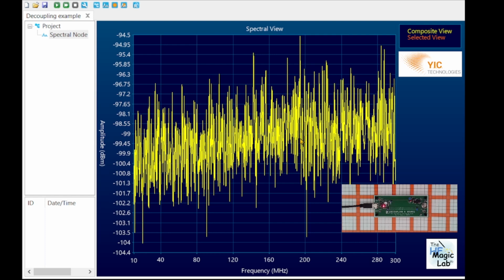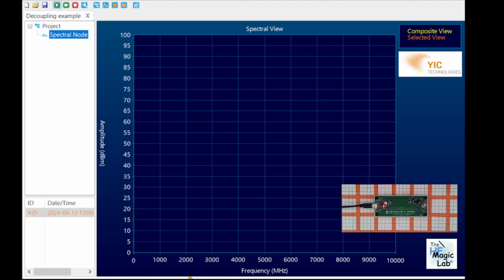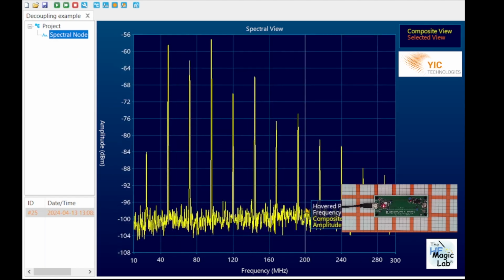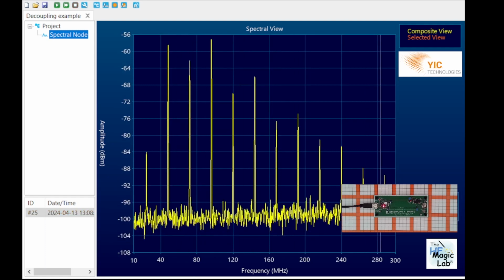Anytime I do click, the cell is activated or deactivated. But it's not necessary to activate all the cells below the PCB because the activity is well around the circuit. So we make OK and we run the spectral analysis. You can see how the scanner is identifying the activity of my digital system. The first harmonic, 24 megahertz, the second harmonic, 48, and all other harmonics with different amplitudes.